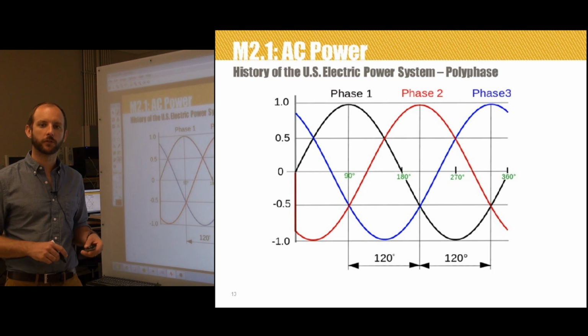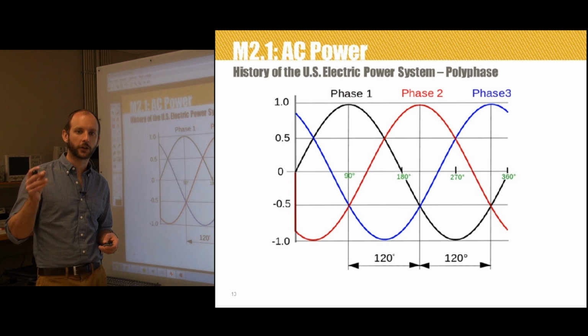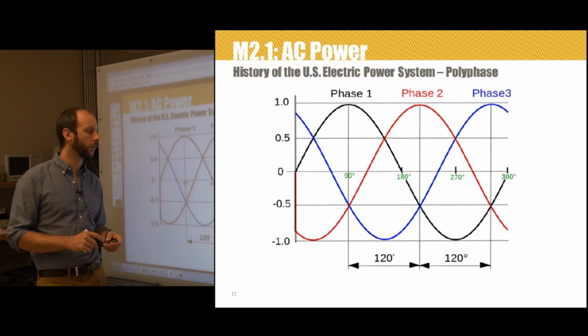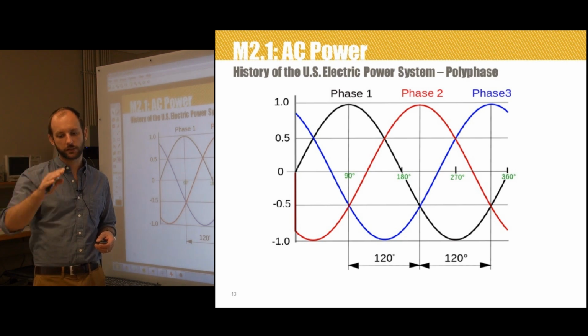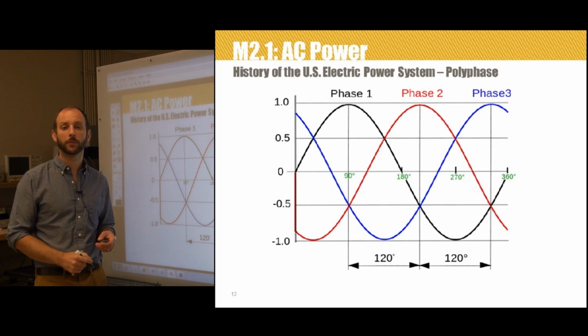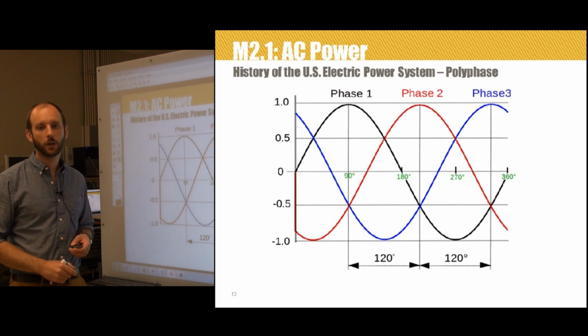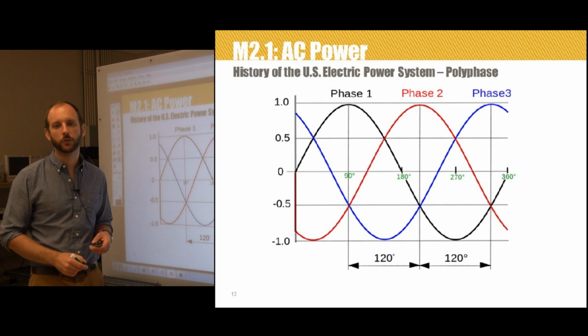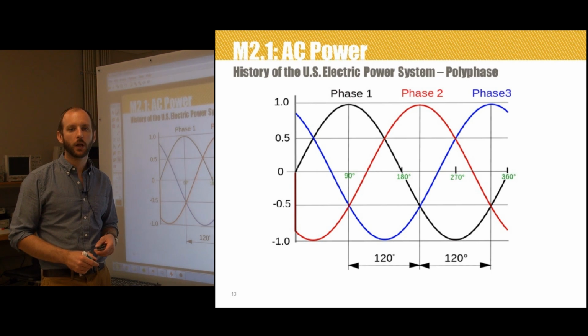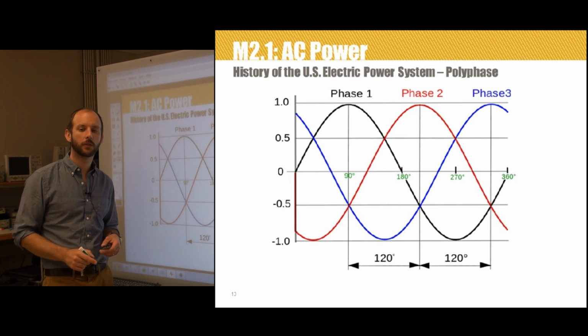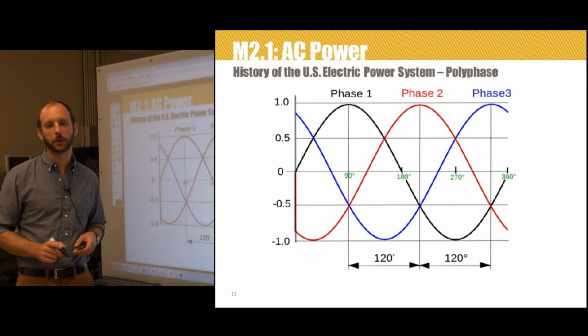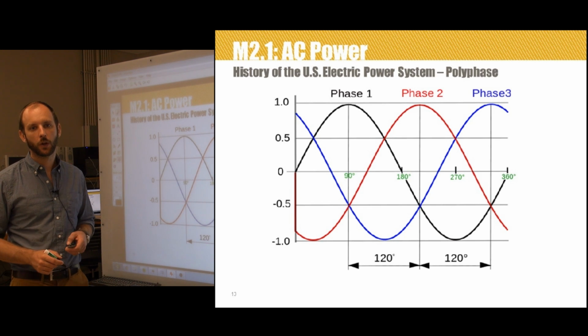The sinusoidal nature of AC caused lights to flicker on and off with the AC cycle. We saw that the AC waveform peaks and then goes negative and then peaks, so there are times when the AC voltage is zero. In fact, the average value of the AC voltage is zero, and that will cause lights to flicker. The sinusoidal nature of the AC system also delivers non-constant power, and this will become very apparent later on in the course. This is a big issue with AC systems.